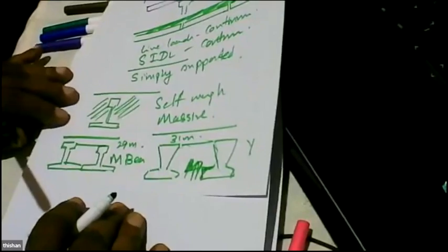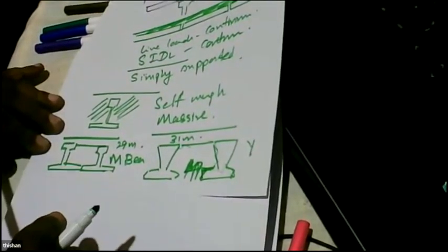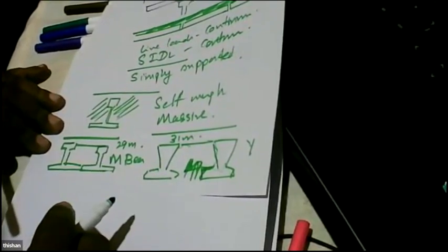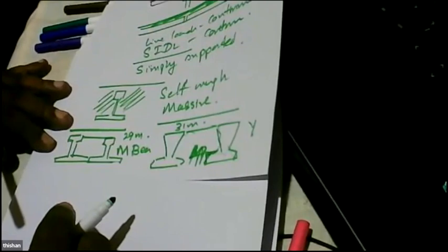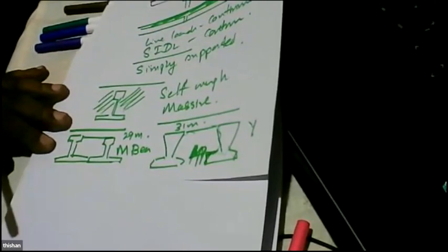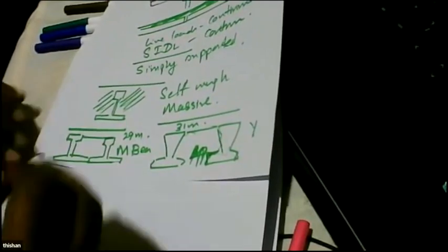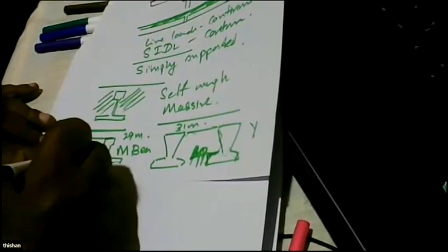And M beams, they are a problem. What is the problem? Now you don't have a torsional stiffness. Earlier, there was huge torsional stiffness because we looked at a slab. But now we are not looking at a slab, because the torsional shear flow in these members will occur within this space.